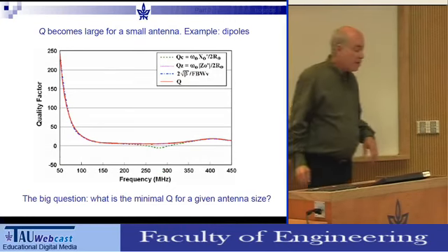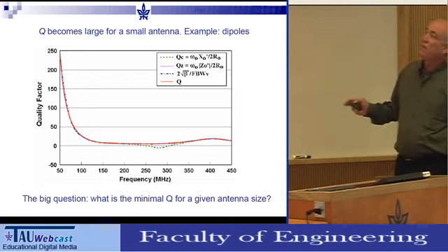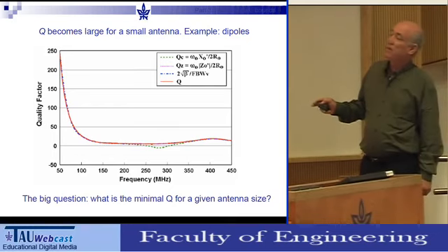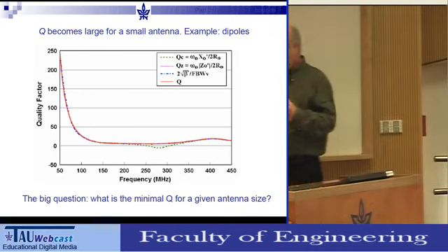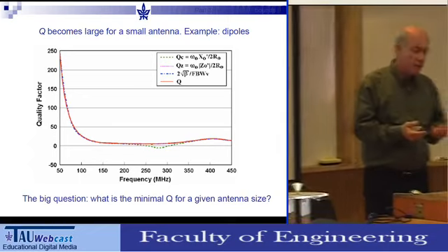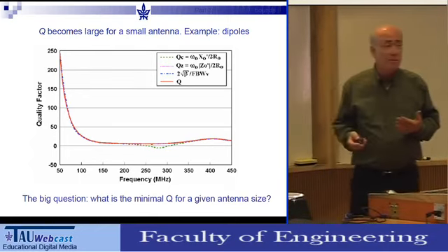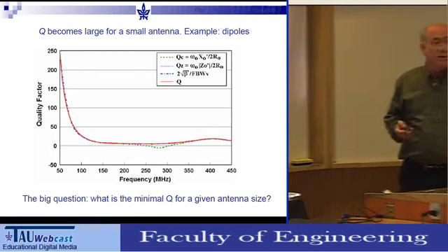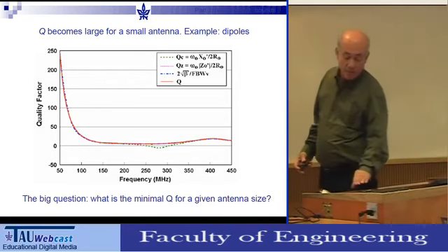The parameter that takes care of just about everything is the quality factor, the Q. There are many definitions. And what we can see is that, again, if you go down with frequency, which is equivalent to reducing the size of the antenna, Q goes up very high. That means that you have, in the near vicinity of the antenna, a lot of reactive energy stored relative to the power that's been delivered to radiation. Simply because, if it's a wire antenna, it's simply a capacitor. So it stores energy but doesn't radiate it. This is the effect of the high Q close to the origin.